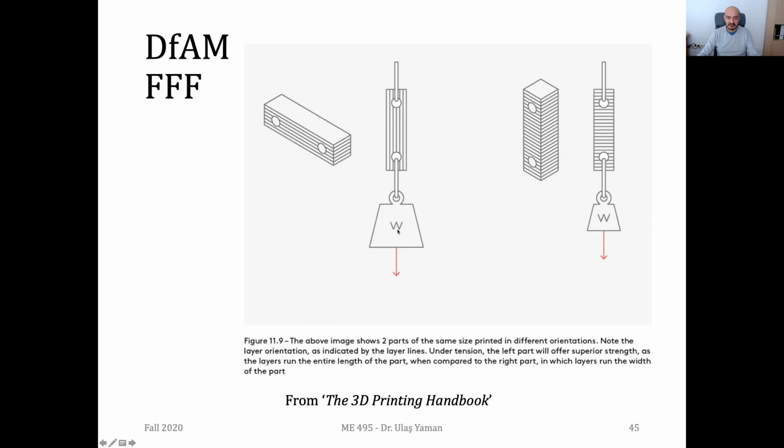If the applied load is in the direction of the slices, then your part will be able to withstand higher loads. But if your application is perpendicular to the slicing direction, then you can carry less loads.